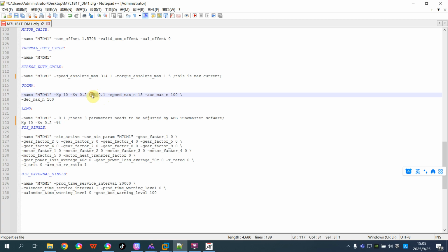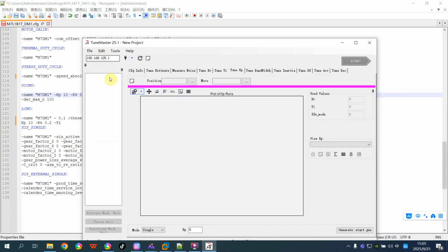For TI, this parameter is typically 0.1. The smaller this parameter, the quicker the response is. Okay, you just have to adjust it one more time. Additional axis, connect to the X2 port and choose axis 7, and you can set the robot position and the linear additional track move position.